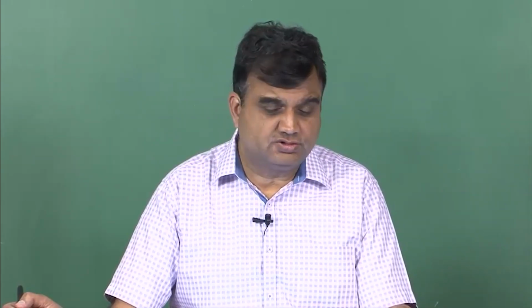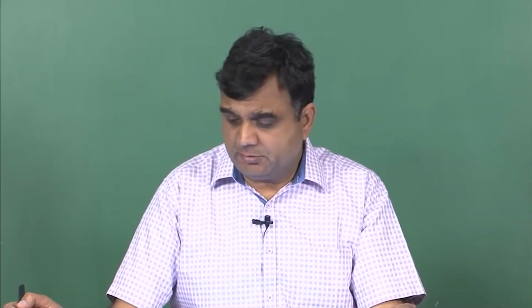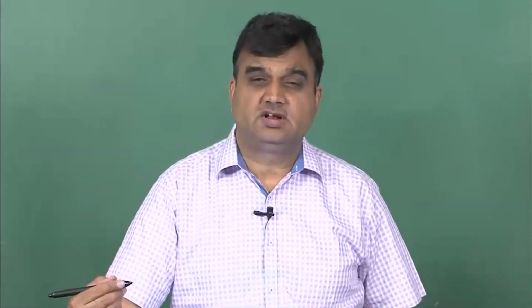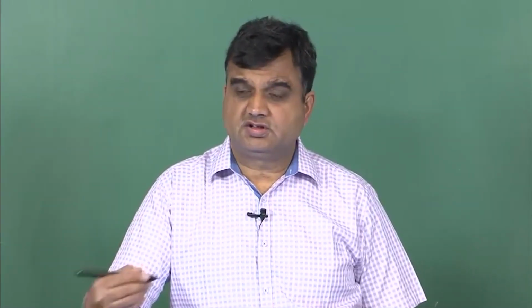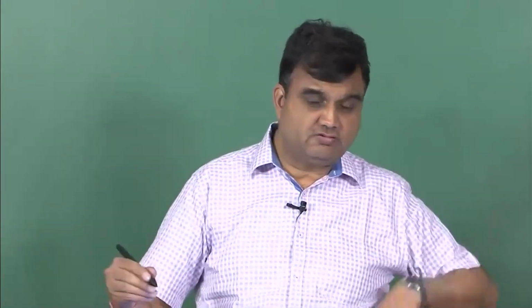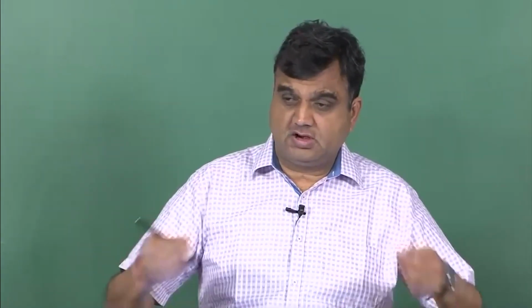Hello, welcome to Introduction to Composites course. Today is the 5th day of the last week of this course, and today we will continue our discussion about quasi-isotropic laminates. Specifically, suppose I have a composite laminate which has glass fibers randomly oriented. That means in all directions the fibers are oriented with equal distribution. So, we would expect that this type of plate will have quasi-isotropic material properties, because it will have the same number of fibers in all directions.